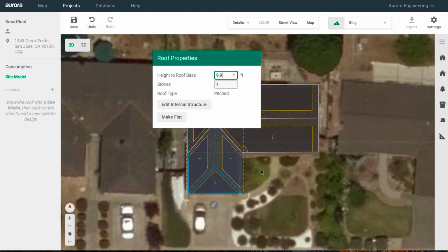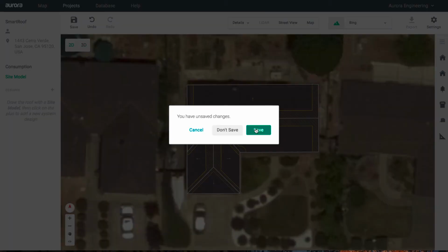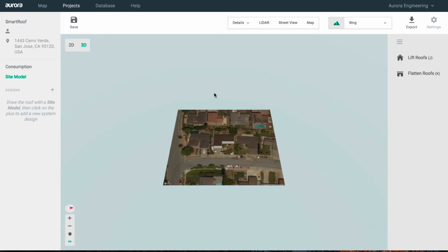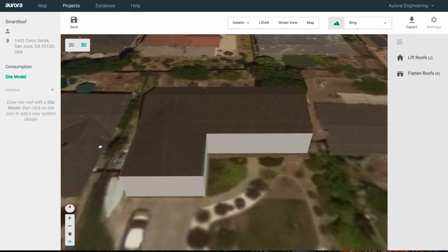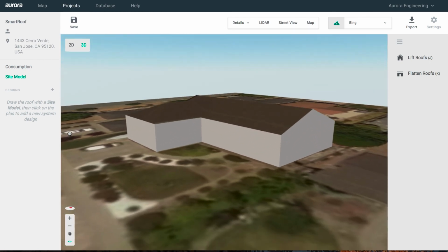And there it has fire code setbacks like a dormer, an A-frame would be expected to, and the 3D model is consistent, as is your 2D model. And that is another very easy way to model these type of buildings. So anytime you have a shape where you can't just quite do it in one go, try breaking it up into two smaller rectangles and doing that.